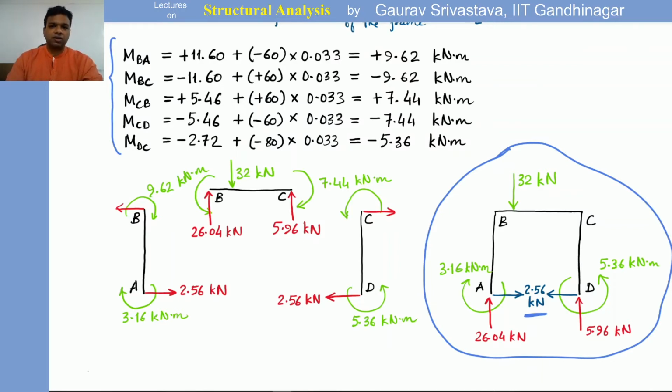Then we found out what was the actual force we ended up solving for due to the assumed moment m bar. And then we found out the scaling factor, and eventually we combine both of them and are able to solve for that. Okay, so this is how the moment distribution procedure can be used for sway problems.